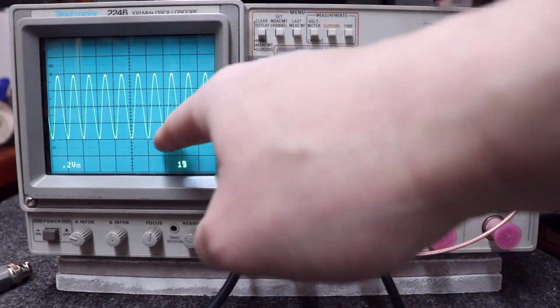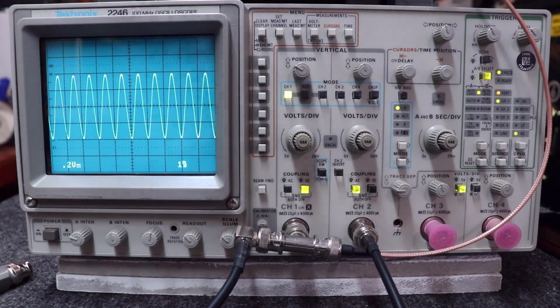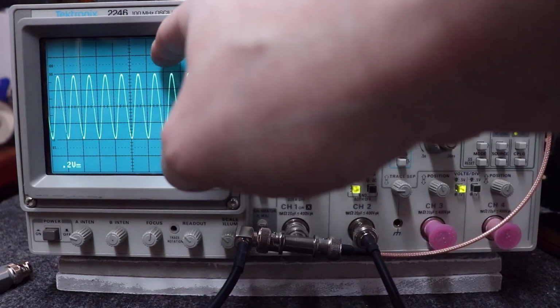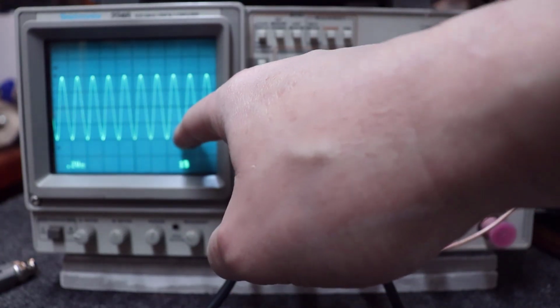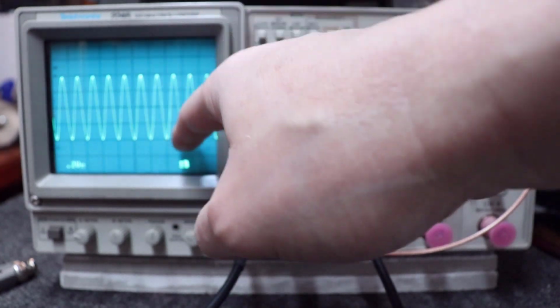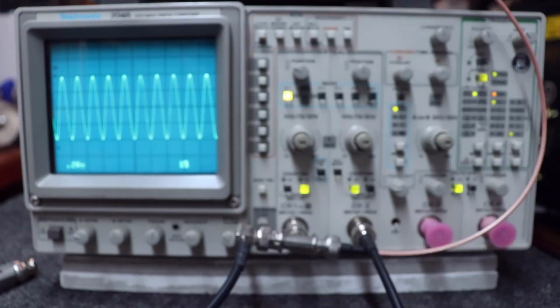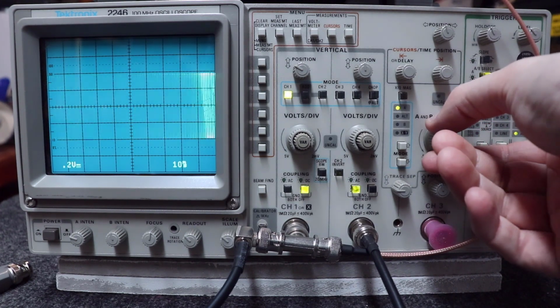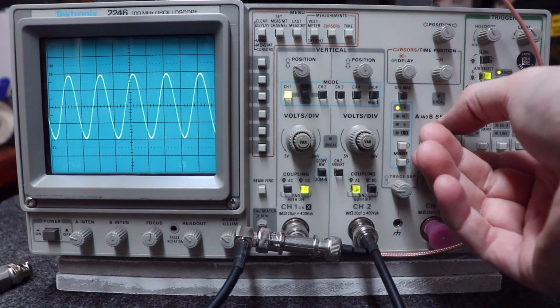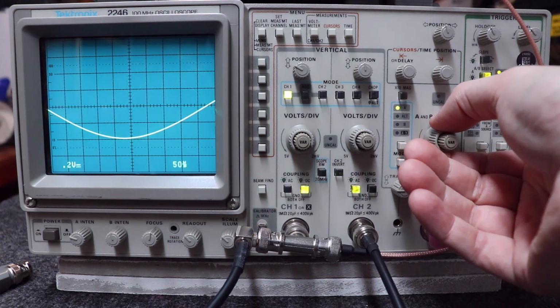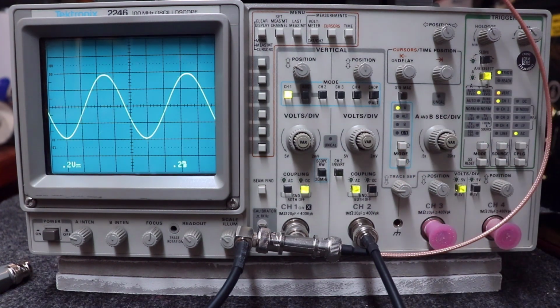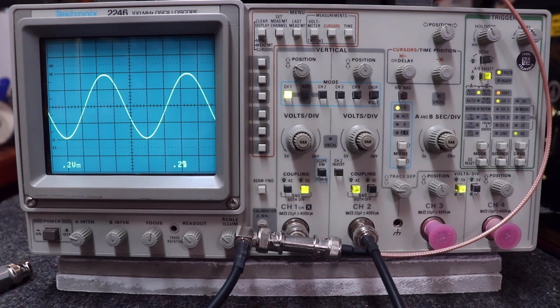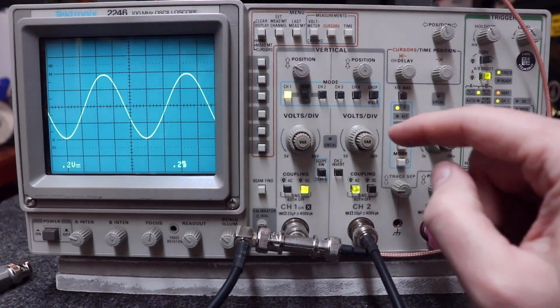Because I'm on a 1 kilohertz signal here, to go from the bottom up all the way back down, or if you started in the middle, up, down, back to the same point, either way, it's 1 millisecond in between those. I can make it really tight between these, or I can stretch it way out and zoom in on this thing. That's a practical level right there for measuring an audio signal.